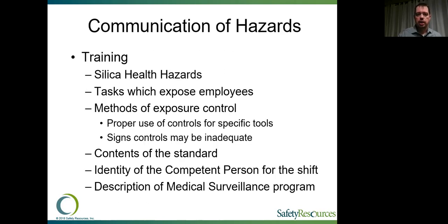For employees, they need to have the training necessary so they can understand what the hazards with respirable silica dust is, and then also make sure that they know which tasks they're going to be performing that would expose them and at what level they would actually have exposure to. Within that, they also have to have a good understanding of what methods they're using to be able to control that dust. So